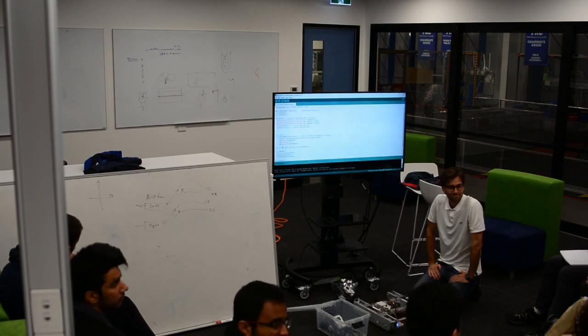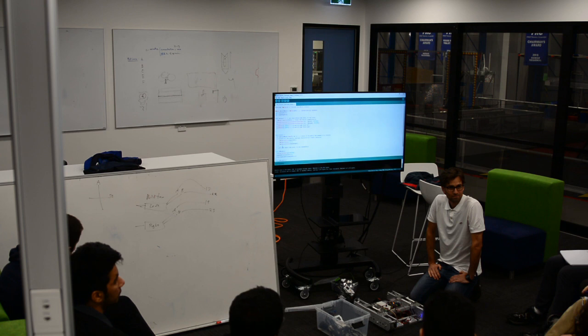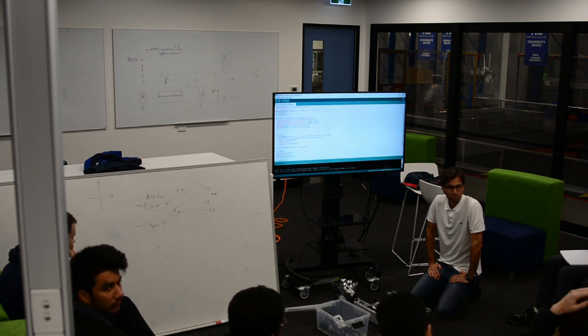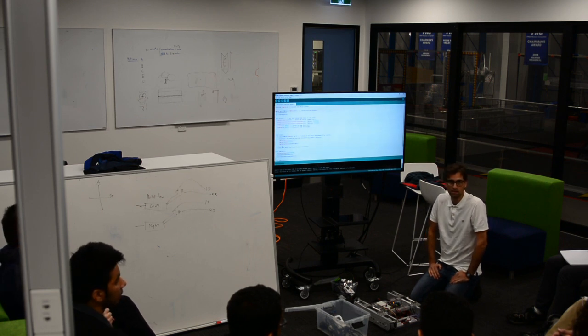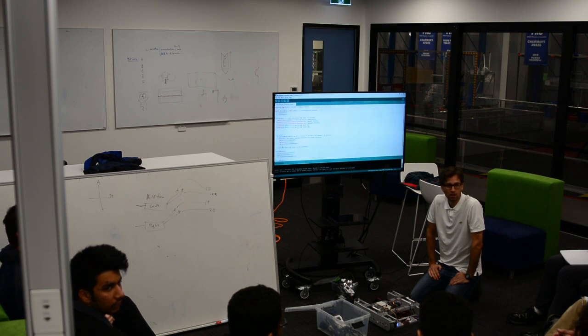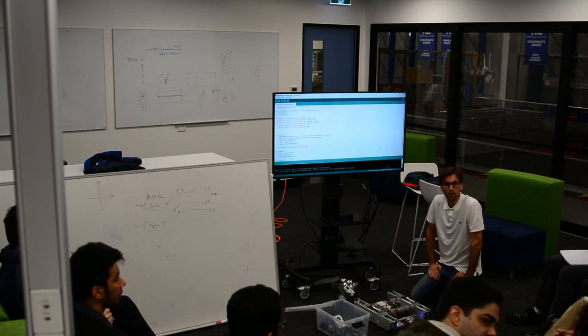Do you know the FRC command-based robot library? No. Okay. I don't know what you get for FTC, so I've got some software for the Arduino that will actually run a series of commands, making a very simple structure for a command: you have a routine that's called and it either returns true or false without saying call me again later on. So what's an example of a basic command? You might have a drive forward command, which will wait until the number of ticks reaches that number, otherwise keep asking whether to move forward.